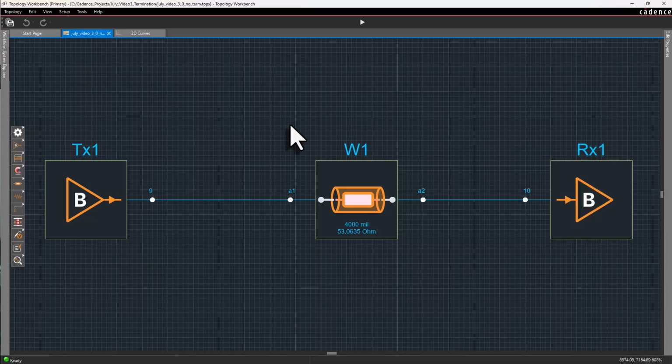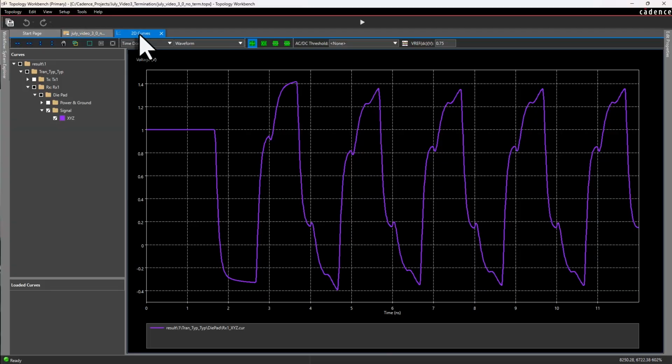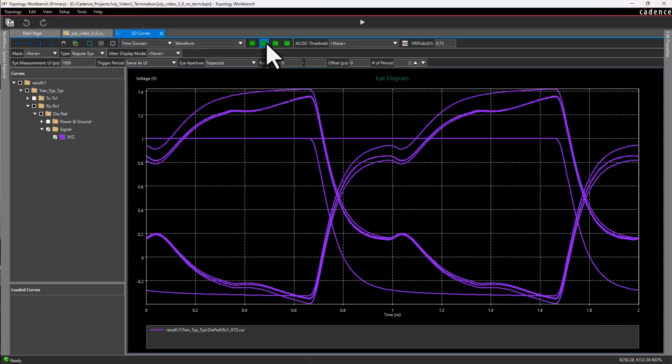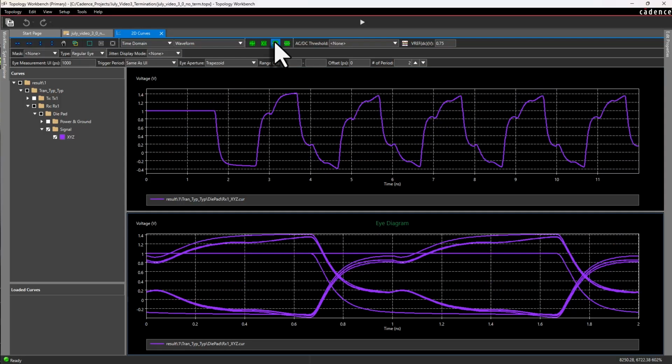Whether it's single-ended or differential pair traces, when you don't have termination, you can get issues like ringing, overshoot, undershoot, blips in the signal, and slow settling times. When those happen, we have intersymbol interference, and that causes the eye diagram to close. That's what we're fixing. Now, on to the termination strategies.